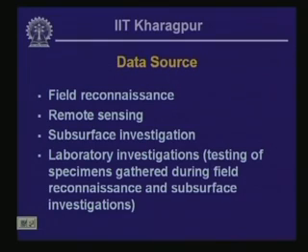The geologic maps available from USGS or Geological Survey of India typically will be at a map scale of maybe 1 in 20,000 to about 1 in 100,000, whereas in important projects one might need a map of a much larger scale like 1 in 5,000 or 1 in 10,000. In that situation, there is no option than to carry out a geological investigation within the project area and prepare a map like the one that was shown in the previous slide.